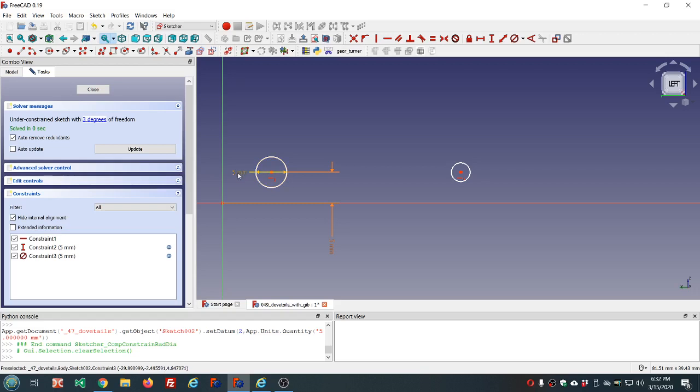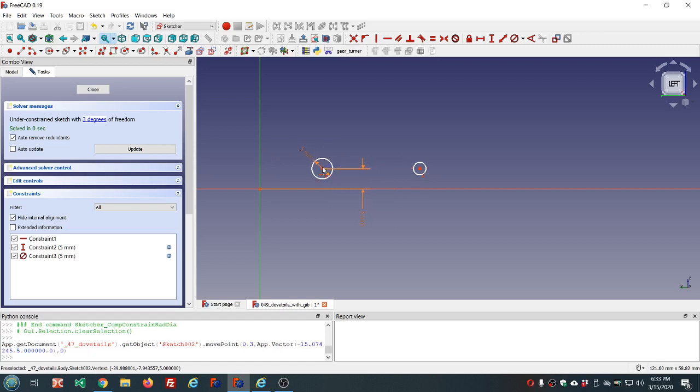Again, this doesn't really matter what that radius or diameter is, because the hole tool will allow you to change whatever you want for your hole. Alright, now we need to lay these out horizontally. So what I'm going to use for this is I'm going to say 1/4 of that pad length and 3/4 of it. We need to make these both equals.